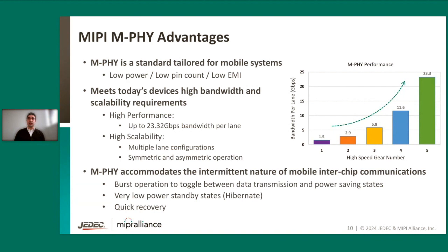Another feature that was added to the specification was the eye monitor. The eye monitor enables live in-the-field input signal metrics to debug possible faults caused by signal integrity without the need of using external measurement equipment. This reduces debug time and greatly enhances the test and debug features of the devices using this specification.